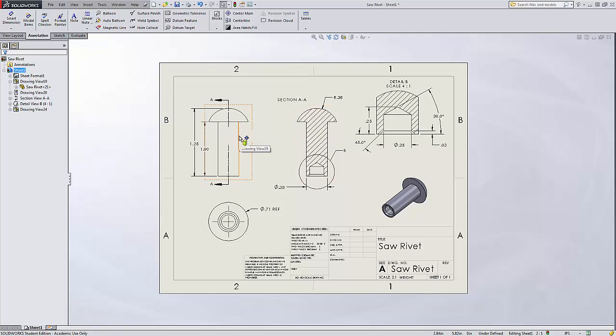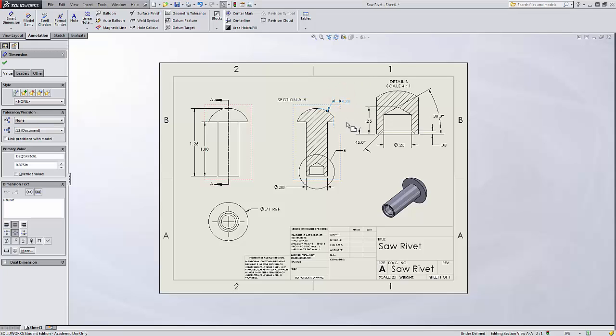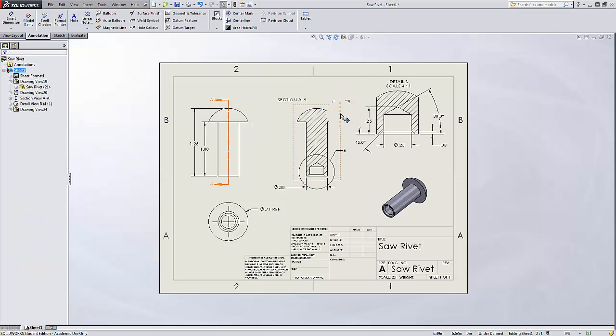That doesn't always happen because of the way the dimension may be in a sketch. So I believe that this 38 radius was done in a sketch that is parallel to this view. So if I take this and I try to put it into this view, it would kind of be flat right down this plane. So I'm going to try to make that happen.